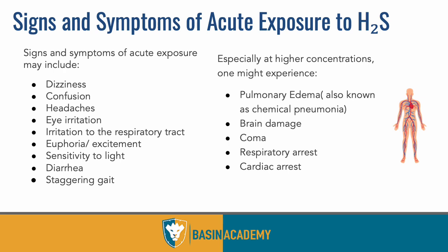So it's going to start sending fluid. The problem is the fluid isn't going to fix the problem like it would with, let's say, an irritant like dust, where it sends fluid, breaks it up, and then you can get rid of it. It's just going to keep sending fluid and filling your lungs with fluid. But the problem is you need air, because the H₂S is actually going to replace oxygen in the bloodstream and then go to all these different organs, which your body's starting to shut down to protect those organs. You're not getting enough air because your lungs are filled with fluid, and it's just kind of a downhill impact at that time.